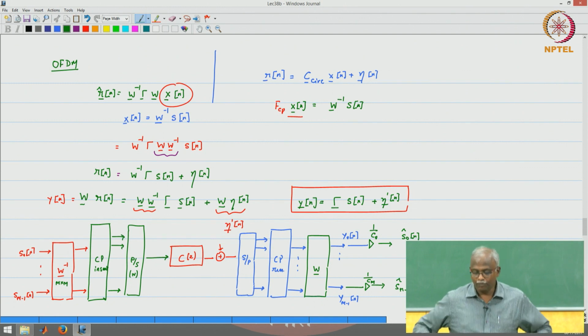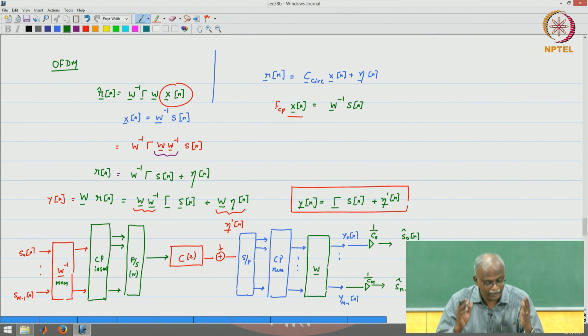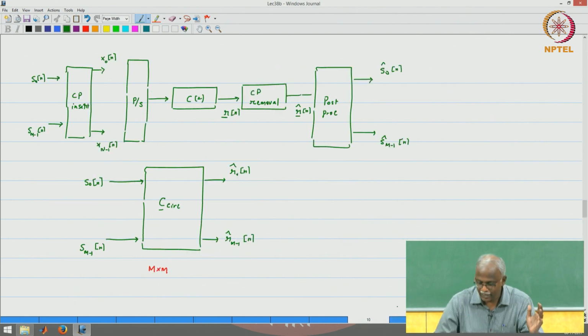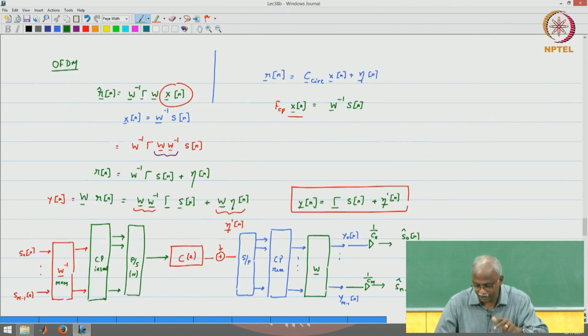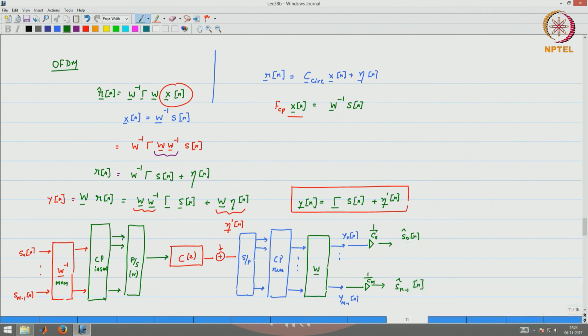Okay, so this is my block transmission scheme, where modulation is done using the inverse DFT, and the reason I use the inverse DFT was because I know that my circulant matrix, which is effectively what is going to come in between my transmitter and receiver, can be simplified, I mean can be written in a diagonalized form. I am taking advantage of that and making sure that at the final stage I just do a 1 over C naught to 1 over Cm scaling.